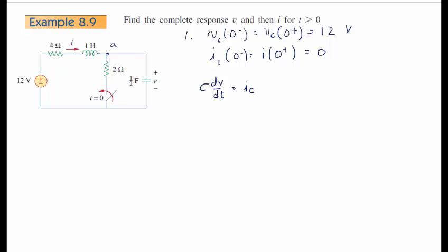Even though this current was initially 0, this part of the switch has closed, and this capacitor is going to start discharging, likely, some of its charge within this loop right here. But we need to find out. I'm not clearly series, I'm not clearly parallel, so I'm going to apply KCL to determine these derivatives, either I or V, that we need. I'm going to apply KCL to this loop at node A, on the circuit at node A.